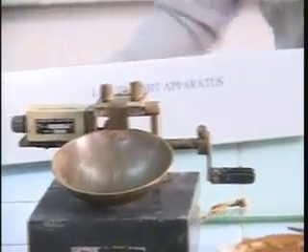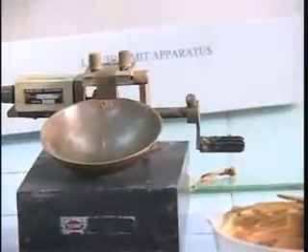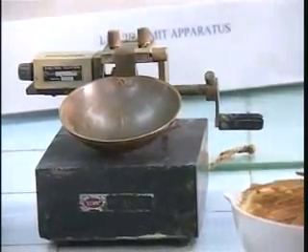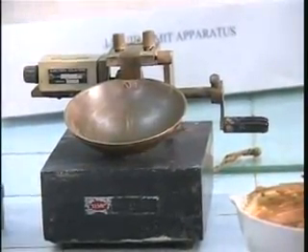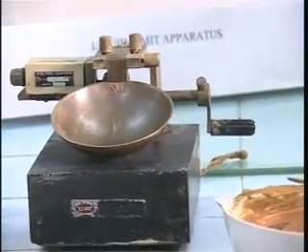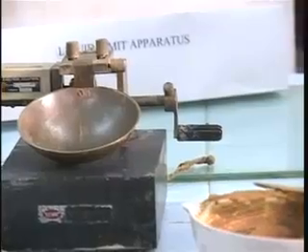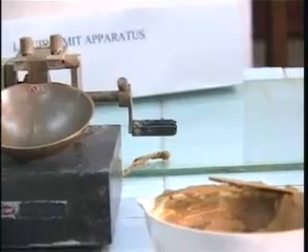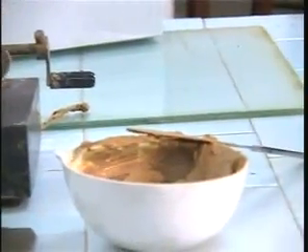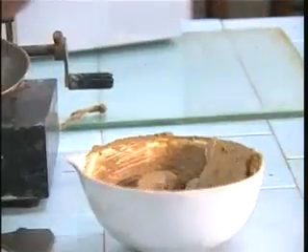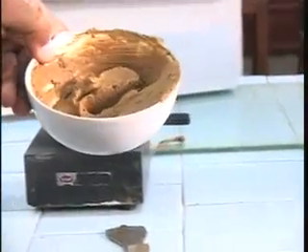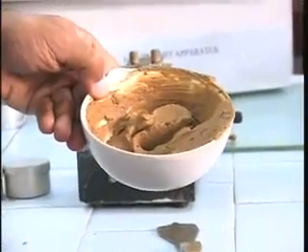Okay, so here we have the demonstration for the experiment which we use for finding out the liquid limit of fine-grained soils. This test is applicable for soils which have grain sizes finer than 425 micron typically. So if you have in situ soil which has some representation of coarser particles, the soil is washed to remove particles which are coarser than 425 micron. What we have here is a sample which is already screened through 425 micron, and this is the sample.